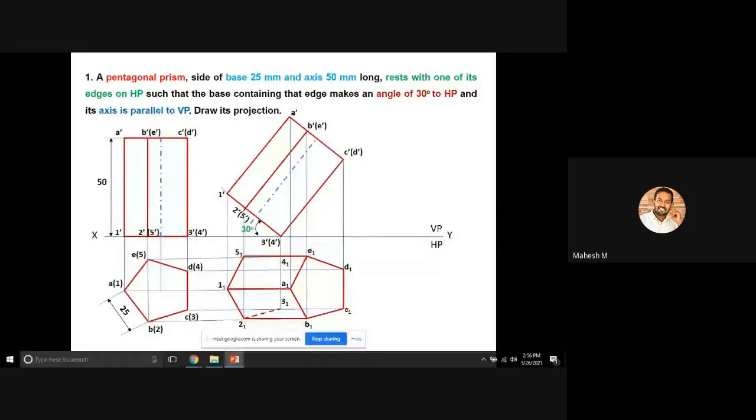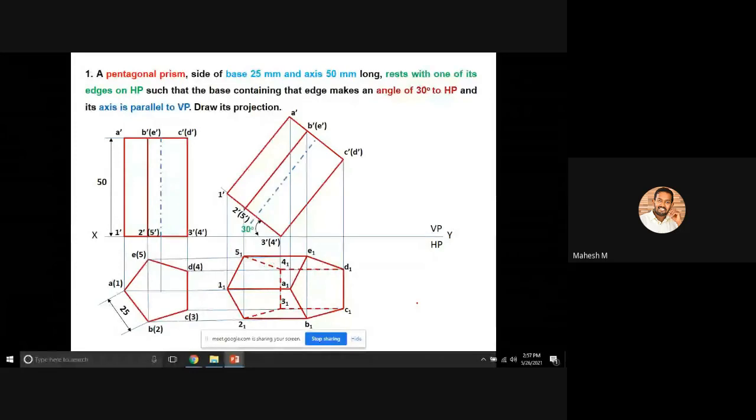Okay, because you have already created a hidden line for 5 and 4 and 4 and 3 and 2 and 3. Okay, so the line coming from the point where two hidden lines connect will be a hidden line. So this line is also a hidden line. So 3 and C is a hidden line and 4 and D is a hidden line. Okay, so this is the inclined top view.